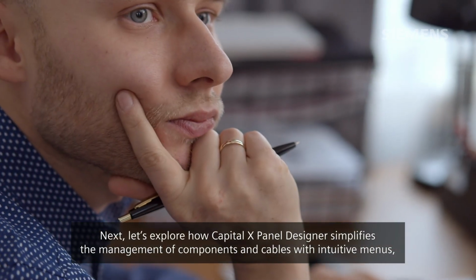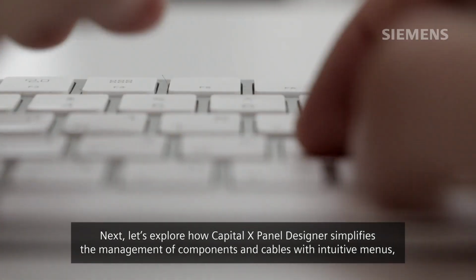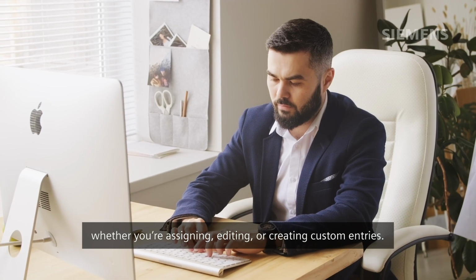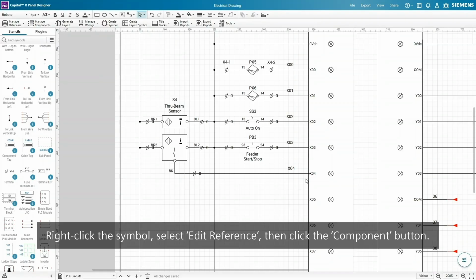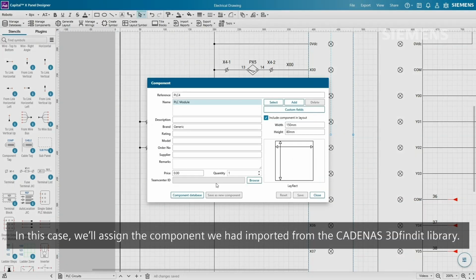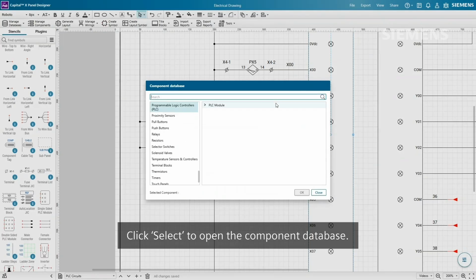Next, let's explore how Capital X Panel Designer simplifies the management of components and cables with intuitive menus, whether you're assigning, editing, or creating custom entries. To begin, we'll edit the component assigned to our PLC symbol by default. Right-click the symbol, select Edit Reference, then click the Component button. In this case, we'll assign the component we had imported from the CADNAS 3D Find It library. Click Select to open the component database.